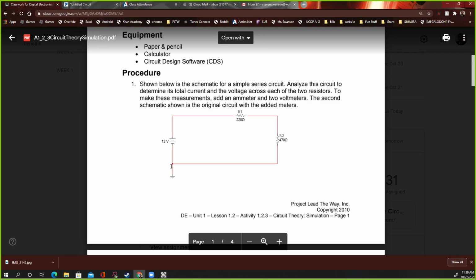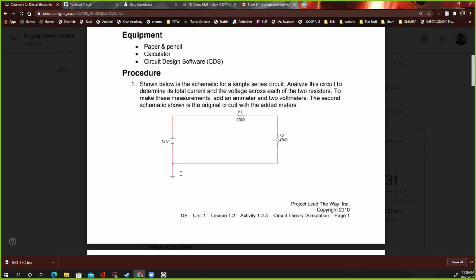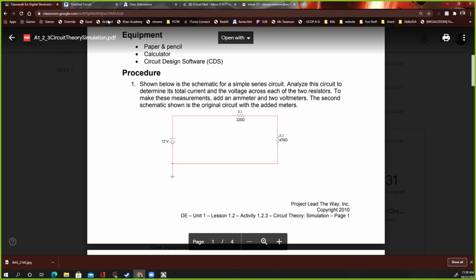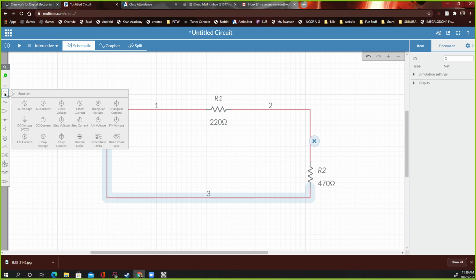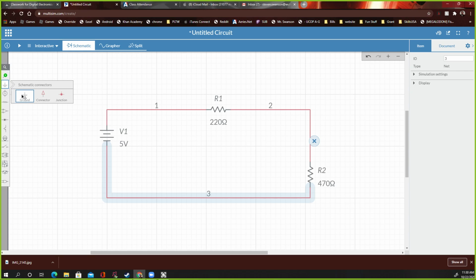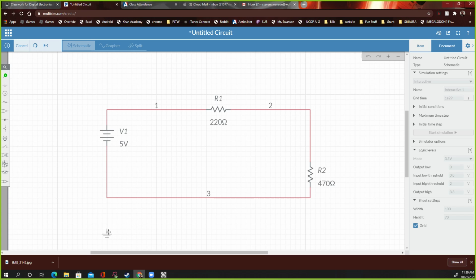But don't forget this ground right here. Do you guys see there's a ground right here? I think it won't work without that. So pay attention to that little piece hanging. That's a ground. And because this is an analog circuit, you need that ground. So it should be under the power stuff right here. I clicked here and I don't see it. Oh, there's a ground right there. I see it. Ground. There we go. It's right here. So click ground. And we'll just click here.